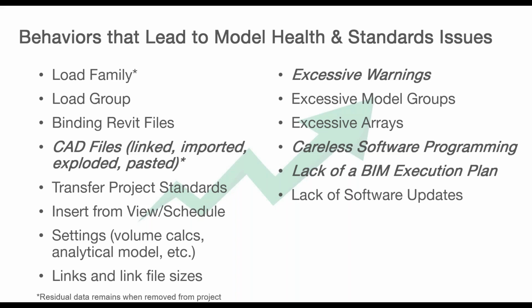So always be aware that with CAD files, there is a consequence to bringing them into your project, especially when you import them and explode them. As one of my former students said a long time ago, he called it shrapnel, right? When you explode a CAD file in your project, you will end up with Revit shrapnel. And I really like that term because he was absolutely right about that.